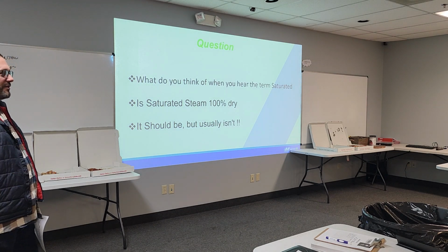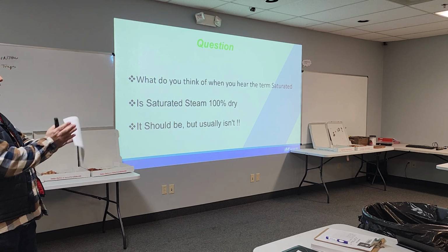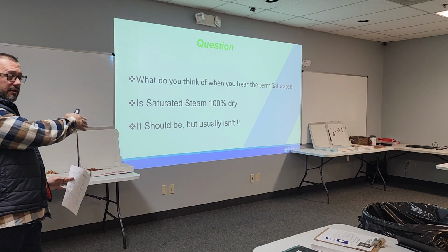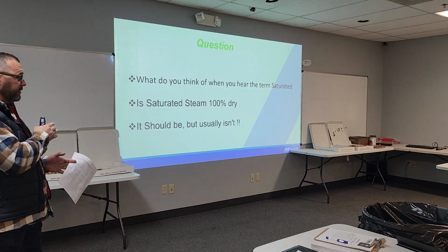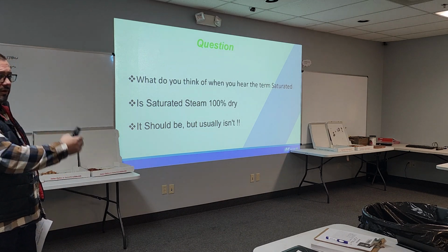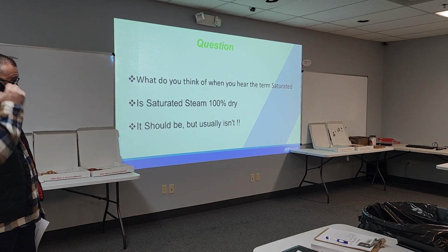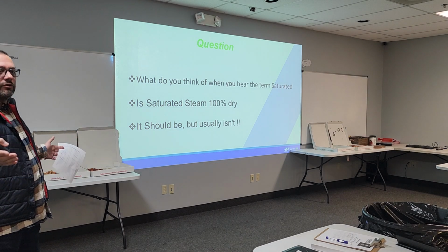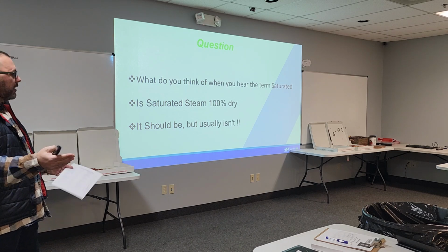And as I was taught by my mentor, when you get a phone call for a steam trap, you're kind of at a fork in the road. You need a drip trap, or you need a process trap. If it's a drip trap, it's a real quick and generally easy conversation. Now, what you'll hear a lot is guys will say, "Oh, I don't know if it's a drip trap or a process trap."